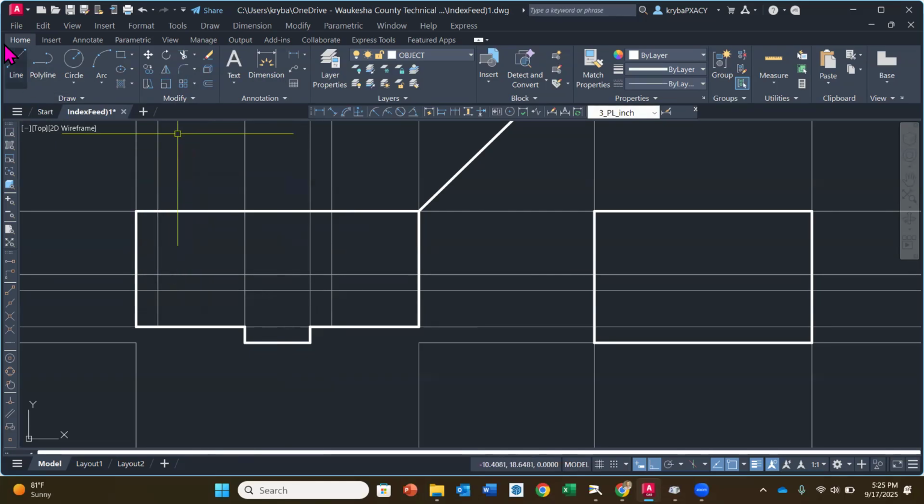Okay, so now the line that I'm going to draw on the object line layer, I'm going to start where I just created that 0.25, go down to my main, go over to my 1 inch away, down, and then over. And then I am going to also go straight across that section where that cutout is, okay?